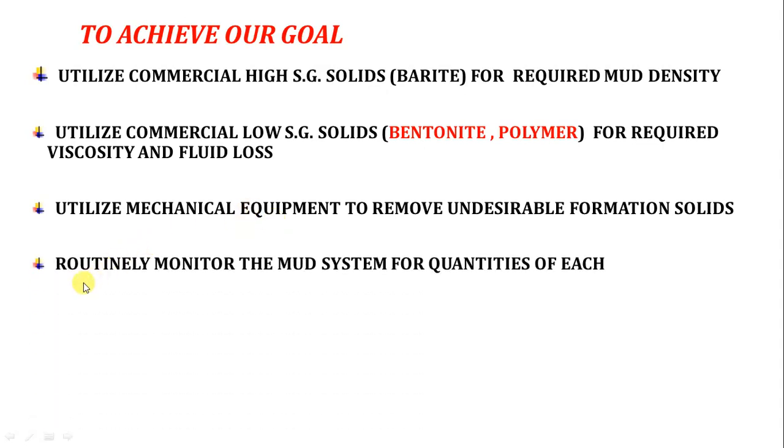Okay. Number four, we have to routinely monitor the mud system for quantities of each, by making solid analysis. So the solid control benefits, for example, why are we making solid control? We are making control over the solids in order not to increase. Why? Number one, because the lower the solids, the higher the penetration rates.